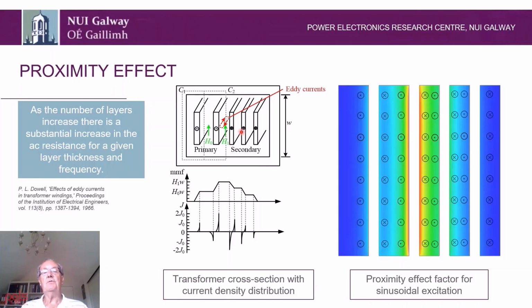Now, when we go to the secondary, the current is in the opposite direction, so it'll subtract from what was there already. And since there are 3 turns in the secondary, we'll decrease it in 3 steps by 1/3, 1/3, and 1/3. Now, if we look at it a little bit more closely, essentially we have a higher magnetic field here than we do here. This, in fact, in this case is double that value as we predicted. And essentially the eddy currents will flow to prevent the magnetic field inside this conductor. And it'll flow in the direction that I've indicated here to block the magnetic field.